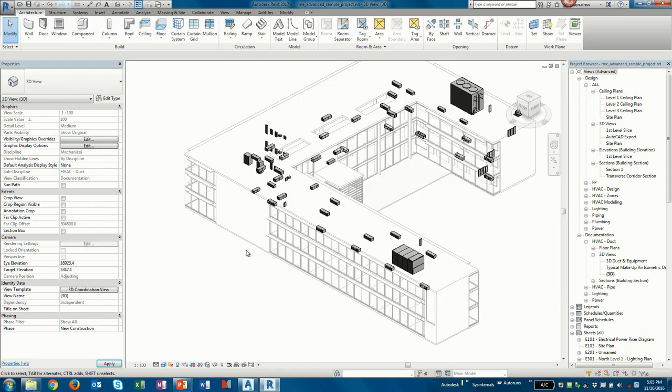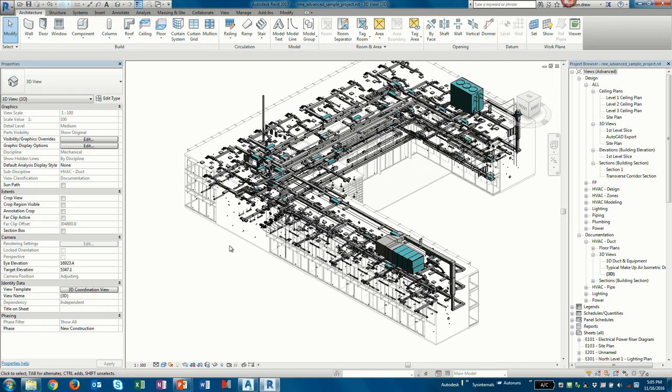I really don't want to export all this into Plant. That would be way too much. Honestly, if I was just routing pipes around the outside of the building or up to the roof, I wouldn't want all that in there. If you dump that out to Plant, it's going to be a very large file, and it's going to take forever for the orthos to generate, because the way the hidden line removal works in Plant is that if pipe's going everywhere, it has to process all the geometry in that model. So it's going to take a long time.